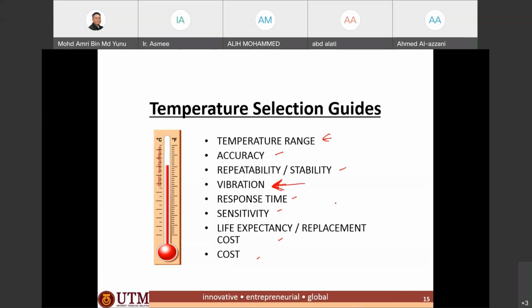A paper mill has rollers, moving mechanisms, stamping, and pressing. A lot of vibration, so you need to make sure that the installation is properly fixed, so that the vibration does not affect the measurement.